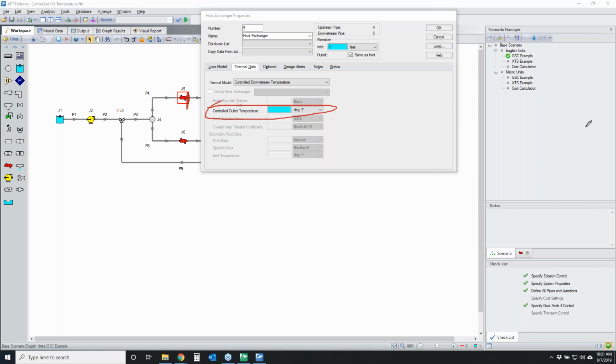Or if you have a spec sheet, you might have other tools that are more sophisticated for heat exchangers, and this will give you a good sanity check if you're actually getting the actual temperatures and heat rates to correspond with what you might have calculated in the other tools. And if they're not, then you might have an issue with how you're modeling your system. So that's one of the simplified methods.